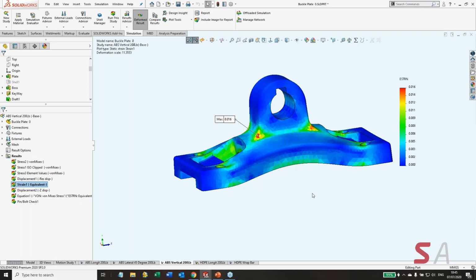And what it's really calculating is the displacement of each node. So when it's done, what it's got is what's called the stress matrix and the displacement matrix. Really the deformation matrix, I should say. Now, from the deformation, what it's looking at is the deformation from one node to its neighbor, and it's backing out of the deformation what the strain is. So those two nodes had a start distance, and then they got a finish distance, and it calculates the strain from that. It's all based upon the deformed model. So strain is backed out from the deformed model.